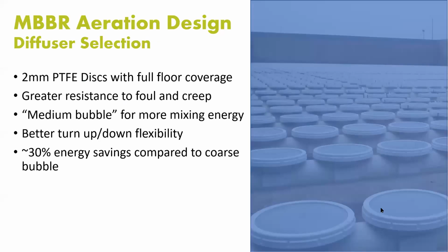So now let's dive into a little bit, we know how many biofilm carriers we need. So designing the tank, we're going to set a volume so that our biofilm carriers are going to fill the tank between 30 and 65% to make sure there's uniform distribution throughout the tank. If we go less than 30%, there won't be enough uniform distribution. You're not going to achieve treatment. You're going to achieve short circuiting. But once we know that we have proper uniform distribution, how do we design the aeration system?